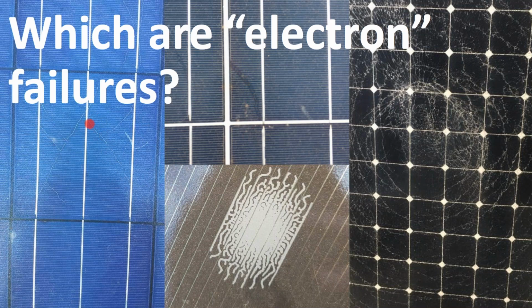If you start to see these things between the bus bars, that's okay, because the current can still get to the bus bars. So you can have these lines going up and down your solar panel, and you're wondering what on earth those are. They're faults in your solar cells, but they might not be causing any production loss. They're not unsafe. Those are where micro cracks are put onto the cell, or a poor manufacturer build quality. You could go all the way back to the manufacturer.